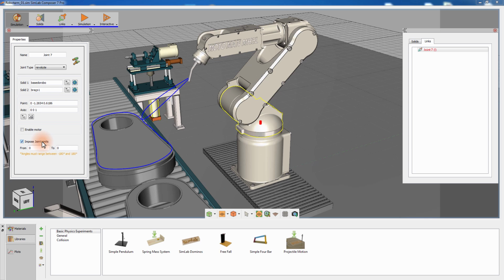Limiting the joint's range of rotation gives you control over the behavior of the robotic arm, and depending on the position of the robot's target in relation to its own position, you can determine those values while keeping in consideration the reach point of the robotic arm. Set the range for this joint to a value of -50 to 50.